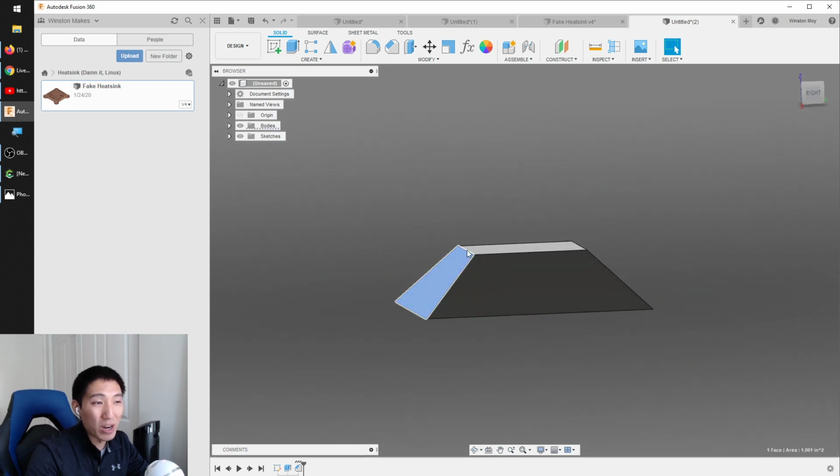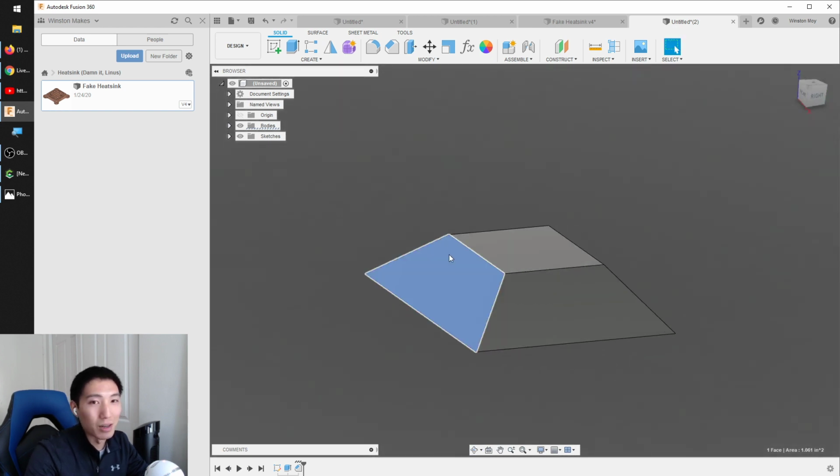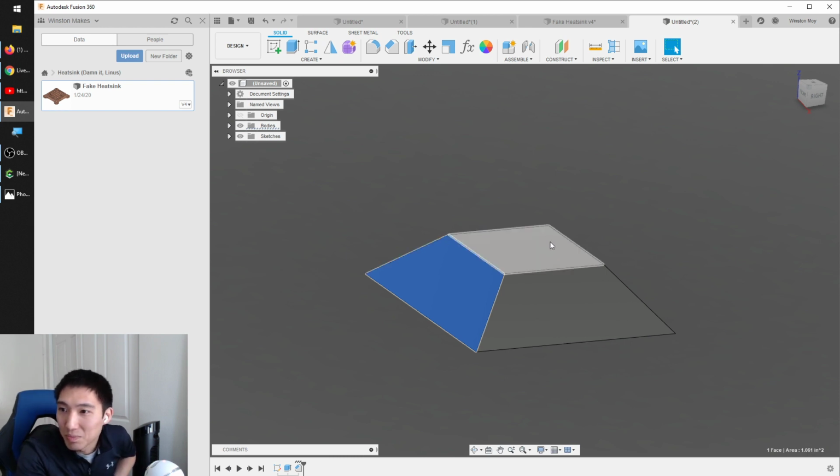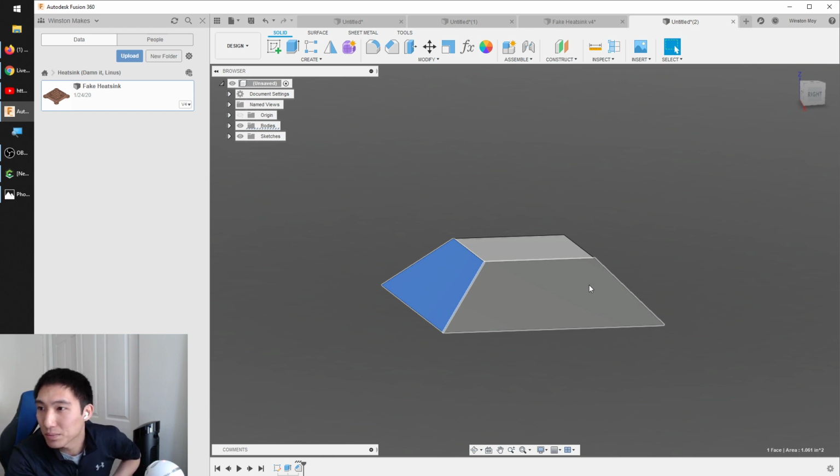This would just get out of the way before the shoulder could even come in contact with this. This would even clear the collet of your router, or probably even the router itself. So it really depends on the kind of geometry you're doing, and just be aware of these kinds of collisions when you're designing.